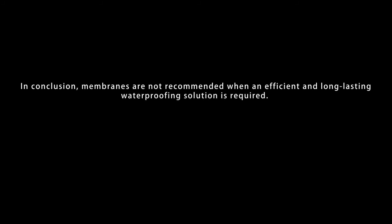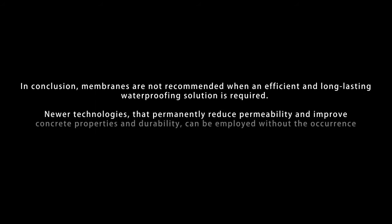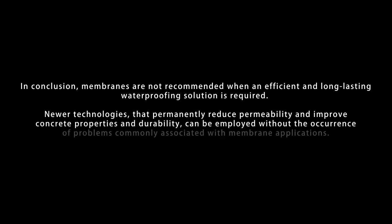In conclusion, membranes are not recommended when an efficient and long-lasting waterproofing solution is required. Newer technologies that permanently reduce permeability and improve concrete properties and durability can be employed without the occurrence of problems commonly associated with membrane applications.